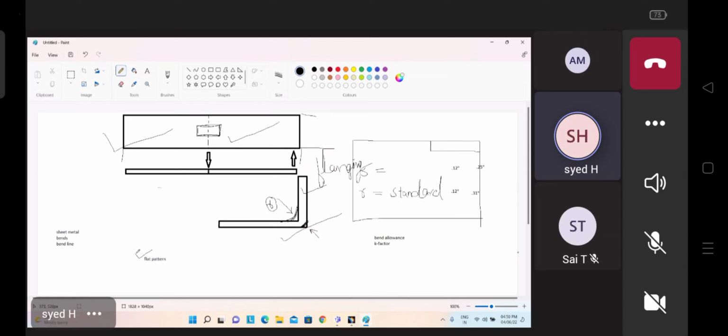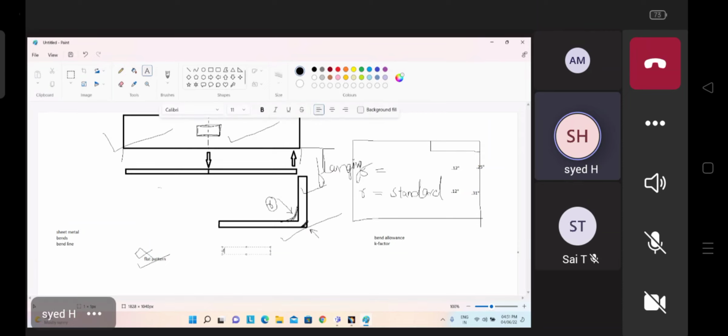I will tell you how to create flat patterns later, mostly in drafting. Usually we create it under sheet metal design, but you cannot see it under sheet metal; you have to see it under drafting, so at that time I will explain this again. Flat pattern is also very easy, and very important. Remember one thing: whenever you are giving the flat pattern, always give dimensions as ordinate dimensions. We have two types of dimensions: one is general dimension, or form dimension.